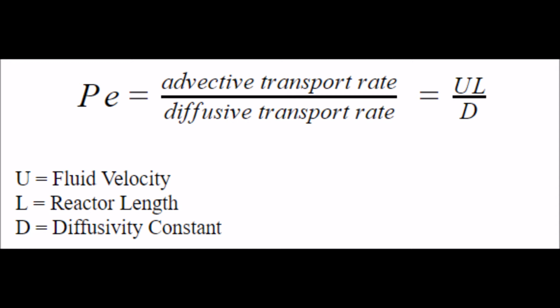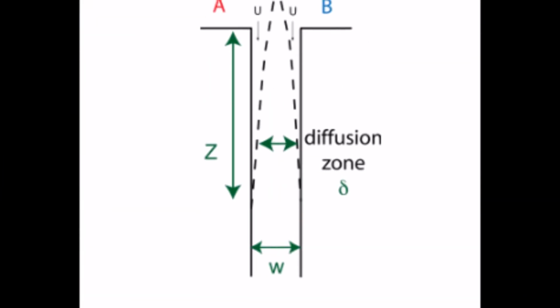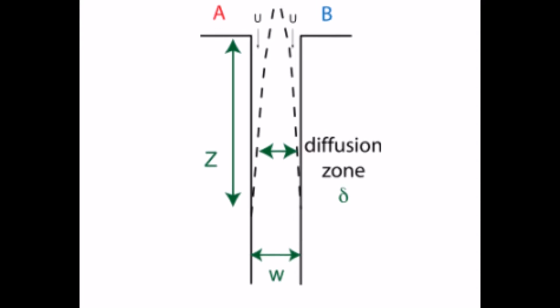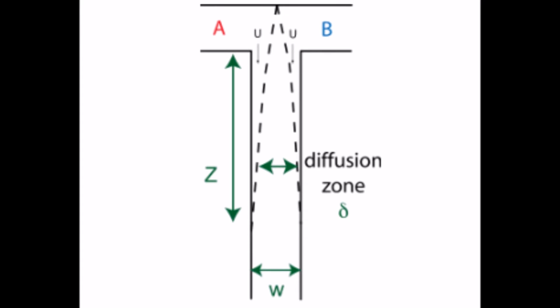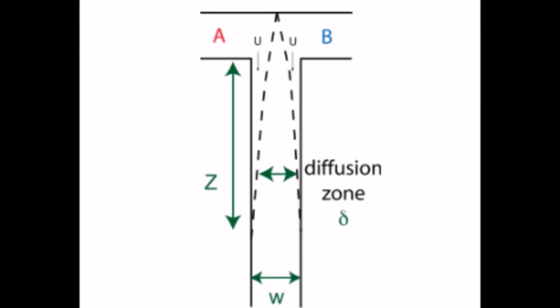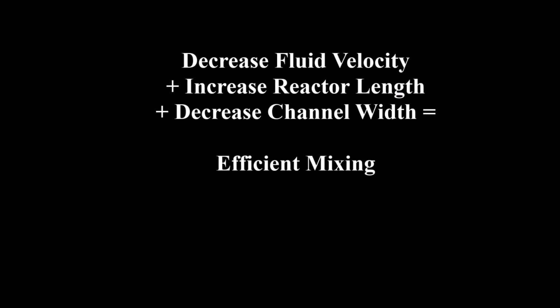In purely diffusive mixing processes, the characteristic length for mixing is proportional to the Peclet number. A linear relationship between the mixing time and the Peclet number implies the channel length needed for mixing increases linearly with increasing fluid velocity. When designing the microfluidic reactor, it was desirable to design so the mixing time increases weakly with the Peclet number. The ultimate goal was to decrease the striation length across which diffusion takes place in order to mix more efficiently.